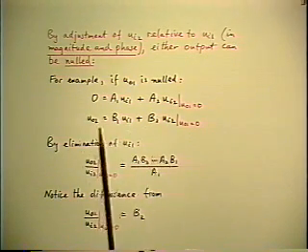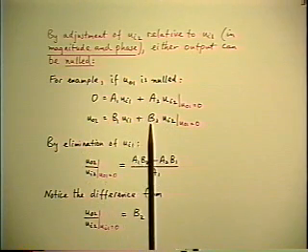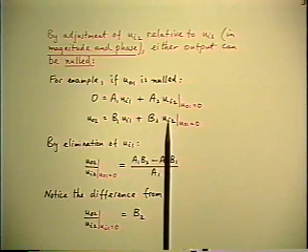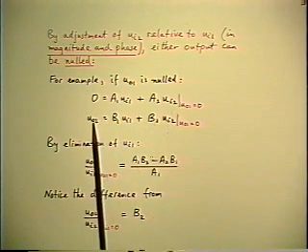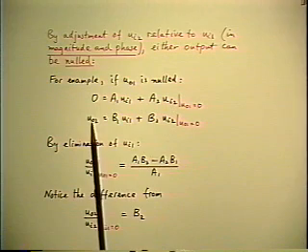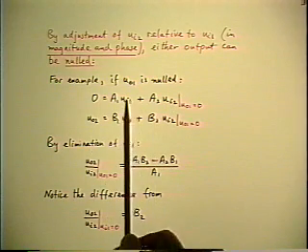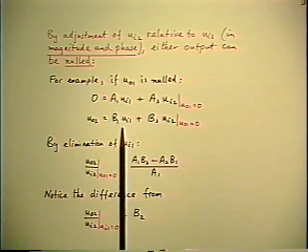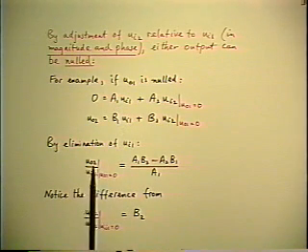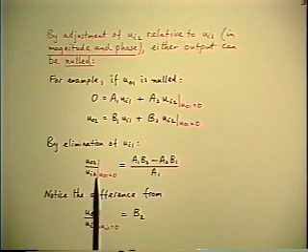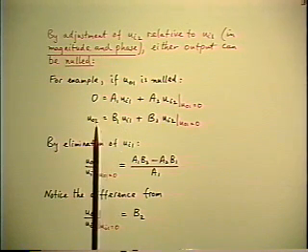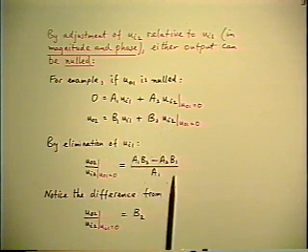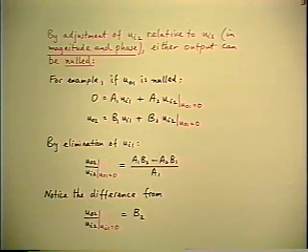And this equation tells you what its value is in terms of the parameters. We have now fixed the relative values of the two inputs, because it's the same two inputs that appear in the second equation. Now I can eliminate input number 1 between these two equations by simultaneous solution. And it's obvious that in about one line, this is the answer you get. Output number 2 divided by input number 2 is equal to this combination of the four coefficients.